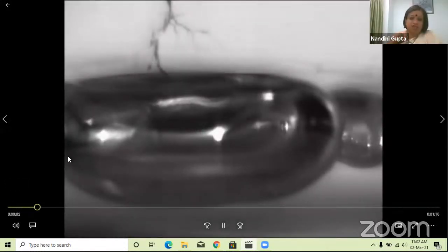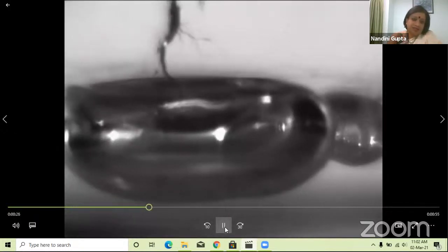So this is the large void that I talked to you about, and you can see electroluminescence happening. And if you observe closely, originally you had a filamentary tree channel like this, but this tree channel is now growing in size. It is becoming thicker and thicker. And wherever the electroluminescence happens, that is the region which grows thicker. So this has become pretty thick.